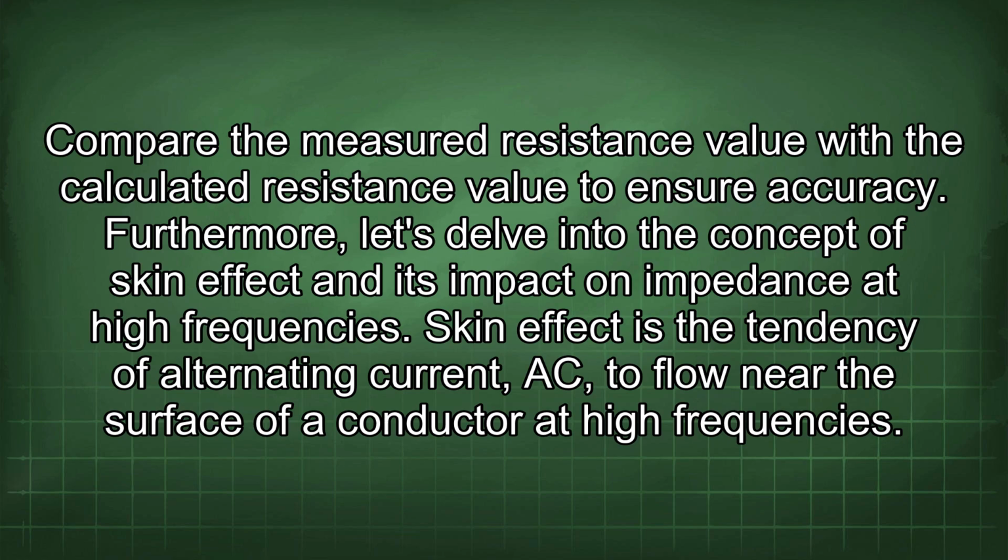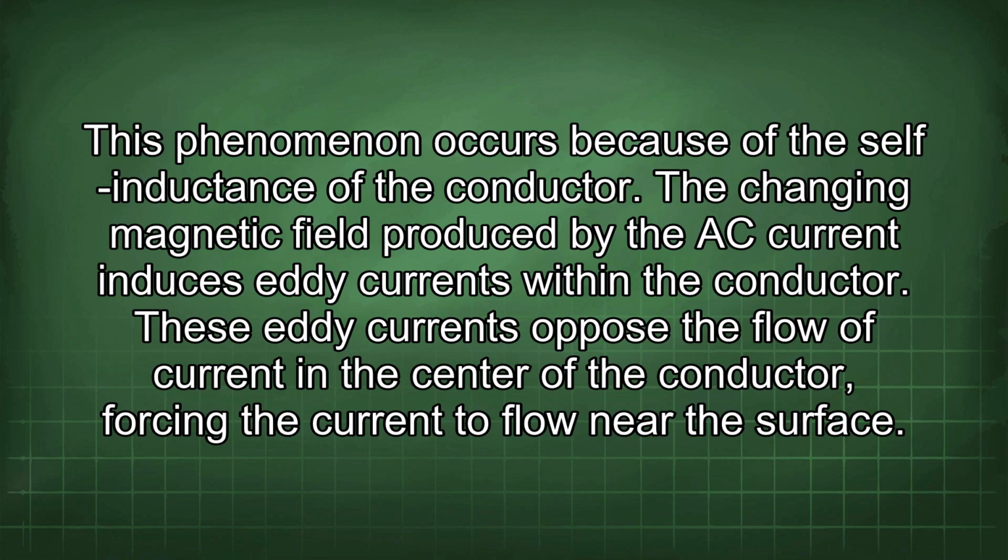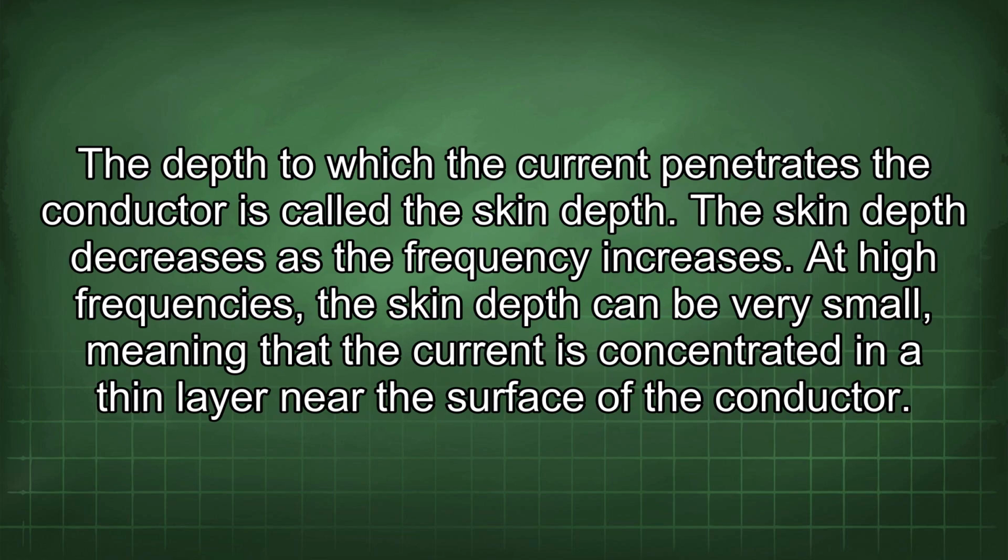Furthermore, let's delve into the concept of skin effect and its impact on impedance at high frequencies. Skin effect is the tendency of alternating current, AC, to flow near the surface of a conductor at high frequencies. This phenomenon occurs because of the self-inductance of the conductor. The changing magnetic field produced by the AC current induces eddy currents within the conductor. These eddy currents oppose the flow of current in the center of the conductor, forcing the current to flow near the surface. The depth to which the current penetrates the conductor is called the skin depth.